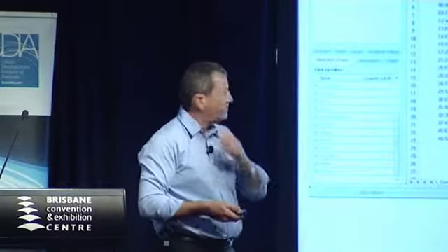The other thing to look at in townhouses is trying to sharpen that structure. So if you can cantilever a balcony by bringing it into an economical length rather than having a structure and an extra external wall line. So they're the types of things that we work with. Now in this scenario, when we reran that model, we came up with $1,255 a square metre.